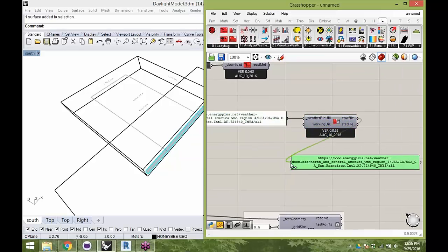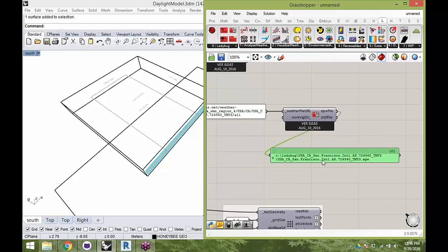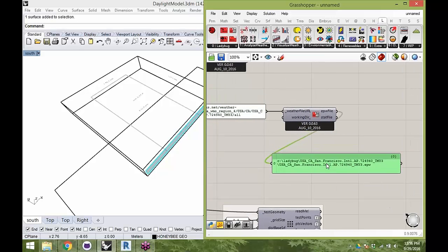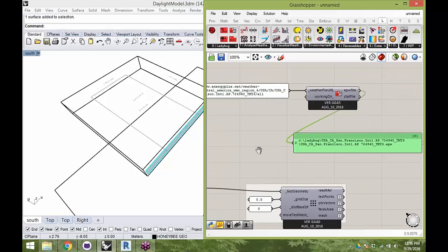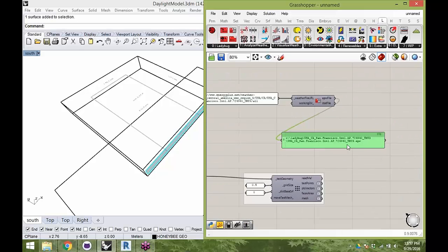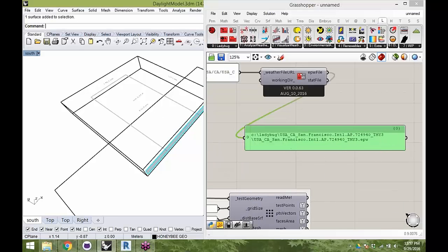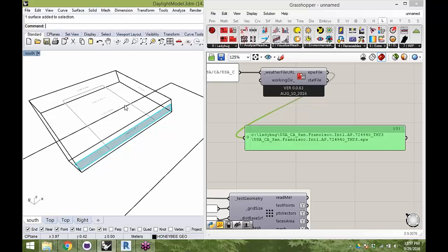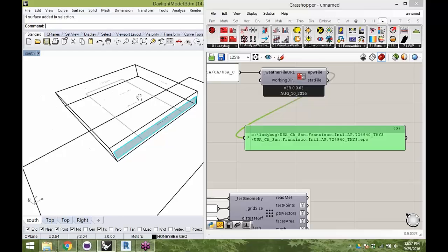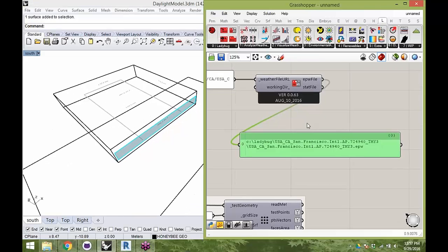All right, so we're now ready to actually go on. We don't just need the weather file itself. If we're going to be running an Illuminance simulation, we actually have to unpack this weather file and the data inside of it and produce a full, what we call a sky, in order to be able to assess what the illuminance is for a given set of situations.